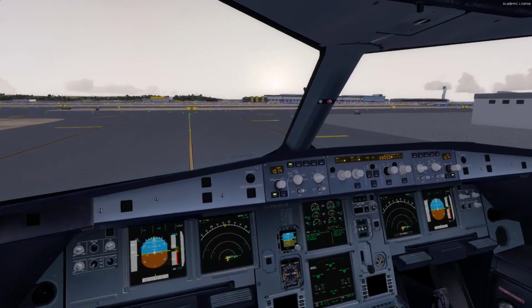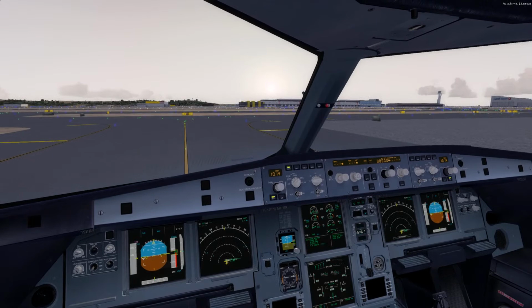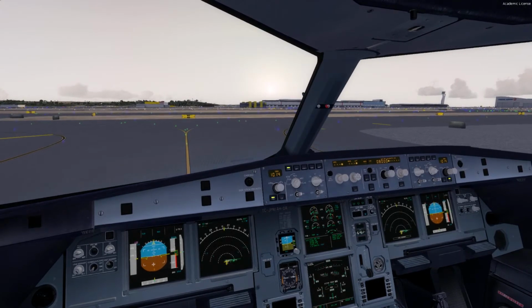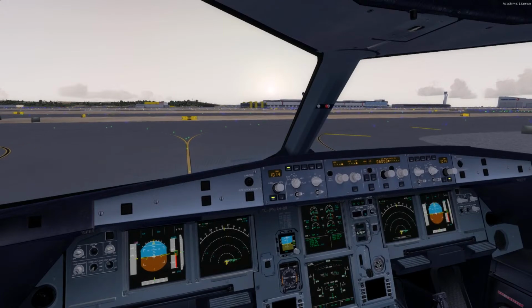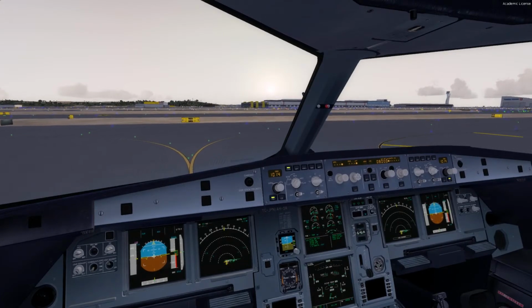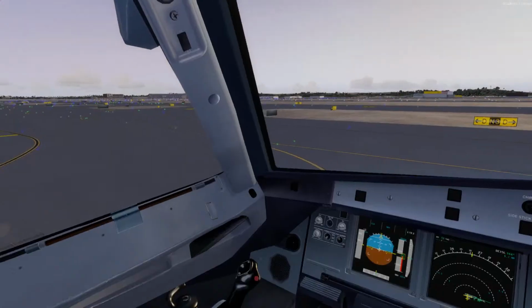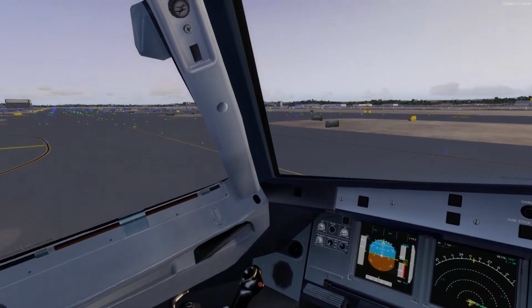We'll check the flight controls to full left, full right, neutral, full up, full down, neutral, and also rudder to full left and full right. We'll need to continue here to...